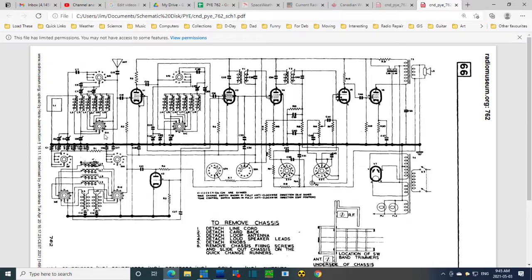So okay, I've got a better grip now on how things are working. Let's look at this oscillator thing, and if we find the big capacitor that's related here, well, I guess maybe it's coming off of this switch, so it's going to be these or these. And why are there two more capacitors in parallel here? Why would they do that? Why don't they just have one capacitor here? You know why? I do know why. The answer is one of them is a temperature compensating capacitor.